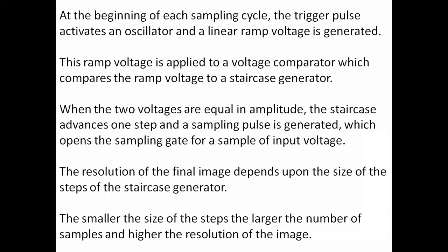And when these two are equal, it will produce a sampling pulse, and that sampling pulse will open the sampling gate for the sampling of the input voltage. The resolution of the final image depends upon the size of the steps of the staircase generator.